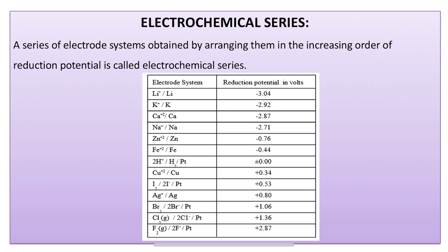If you observe zinc and copper here, they are far apart on the scale. This means that you would never have a copper pipe draining water onto a zinc coated roof. So these are some of the basics of the electrochemical series.